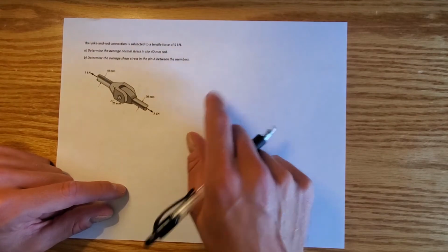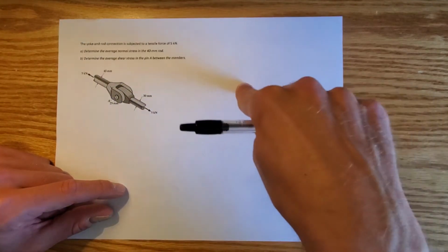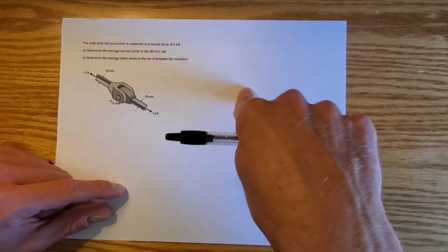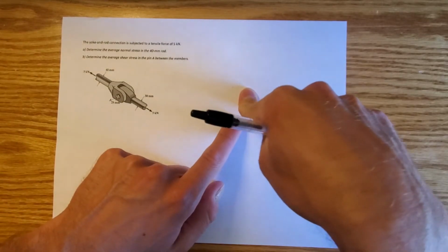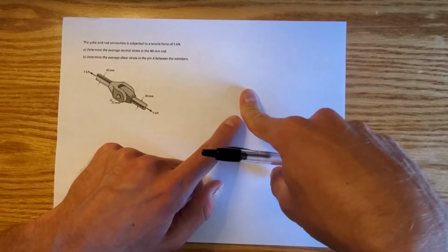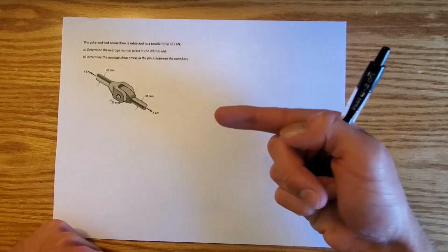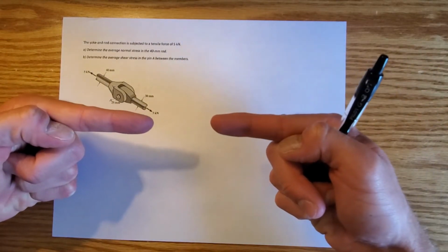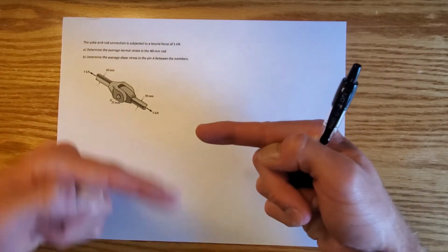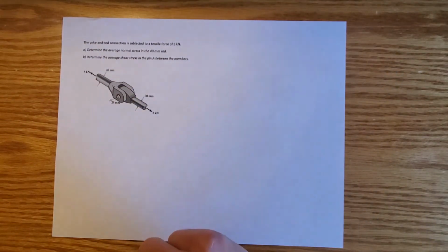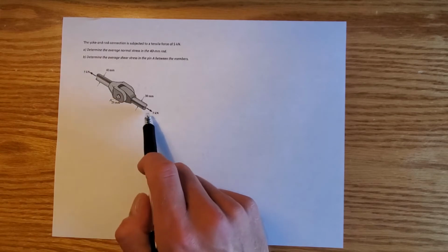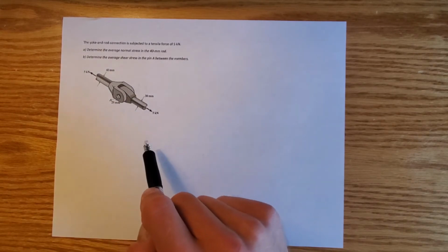Consider this piece of paper here as another example. If I push down on this piece of paper with 1 Newton of force, well, the ground pushes back up. Well, not the ground, but the table pushes back up with 1 Newton as well. So the paper is experiencing 1 Newton from me and 1 Newton from the table, but we don't say that it's experiencing 2 newtons. We say it's only experiencing 1 Newton of compression. So that's what's going on here: it's got 5 kilonewtons of tension.